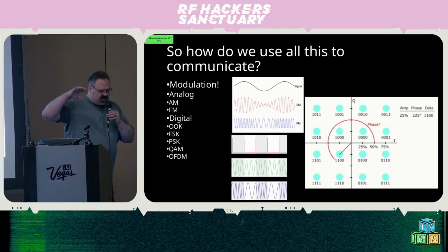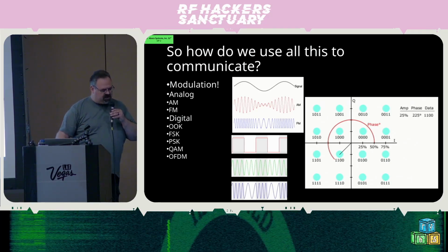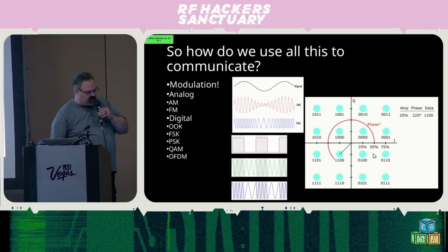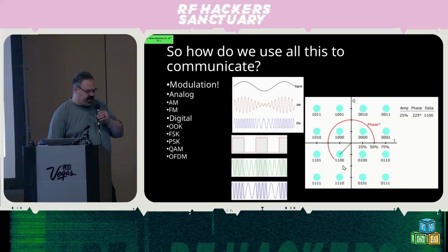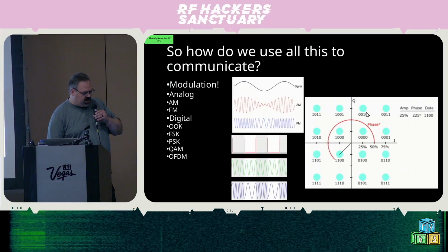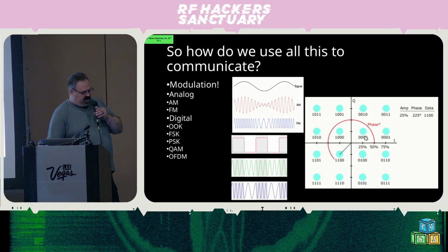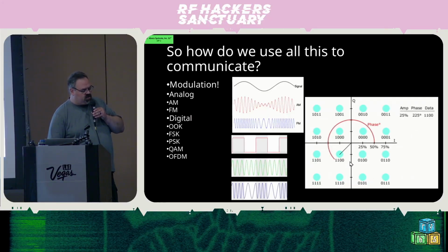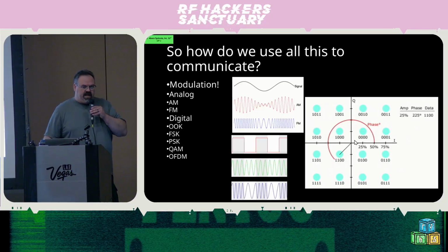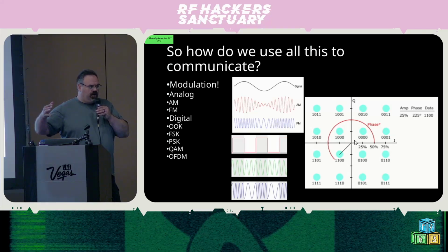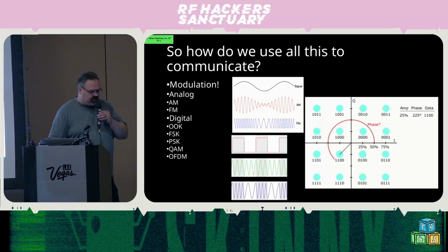So let's say this is quadrature amplitude modulation 16. So we have 16 points, and yeah, the encoding of each of these is based on a different IQ XY coordinate, and it just kind of lets you pack a lot more bits into your signal that you wouldn't have been able to before. The downside is you need a much quieter channel in order to get this to a point where you can decode it. Otherwise, it all just looks like noise.